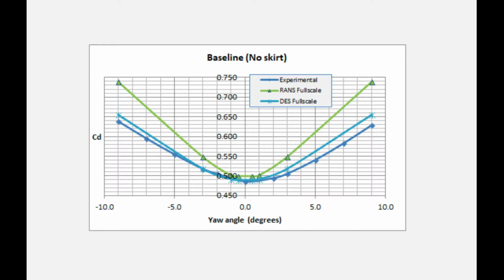The truck add-on predictor recipe is providing two different recipes for the users. There is the steady RANS model and the DES transient model. The steady RANS model is computationally inexpensive and can solve relatively quickly, within, say, around 20 hours, whereas the DES transient can take more than 2 to 3 days of solving. And so it's much more computationally expensive, and therefore the simulation itself costs more as well.